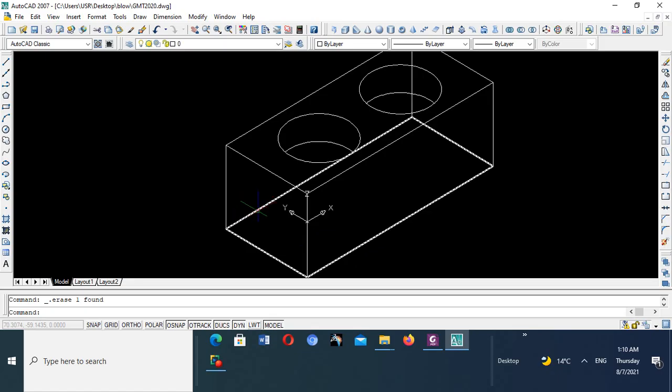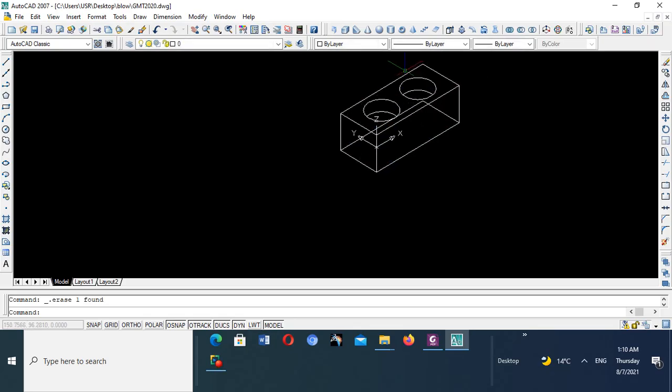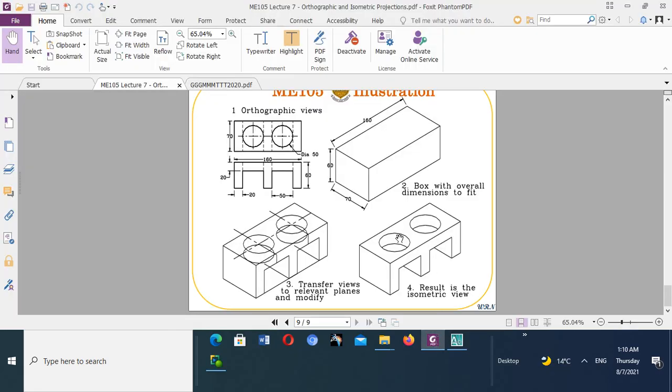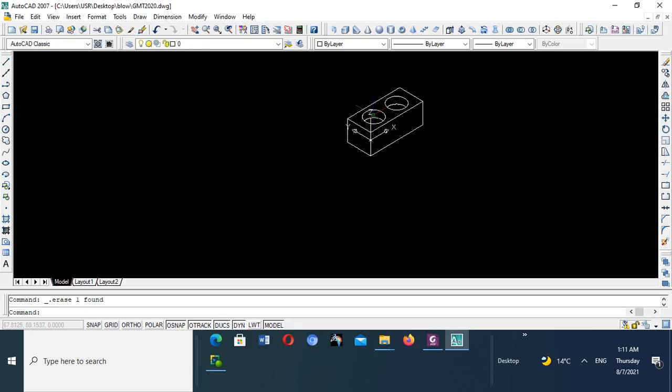Then also, believe with me, this part of the rectangle is not visible. That part is not removed yet. So we remove that. Start with this one. We remove it. Very easy to remove. It's not visible in isometric. You can see here, those edges are not visible. So we want to remove them. This is one entity, so we want to explode it. I taught you how to explode. Now we can remove this. Delete. We can remove this. Delete. We are nearly home. Nice.